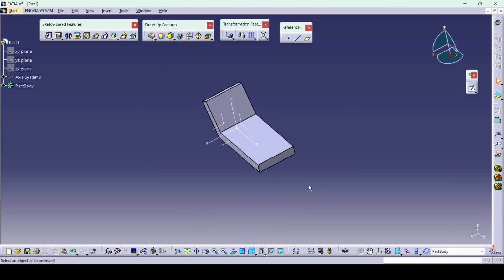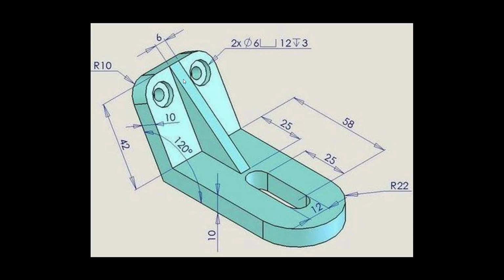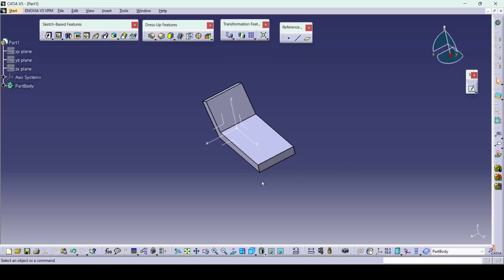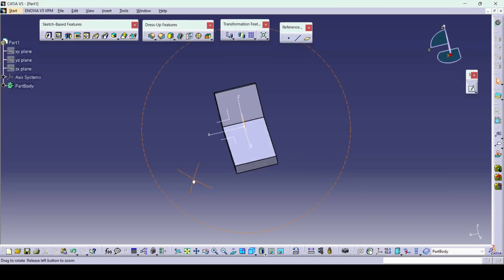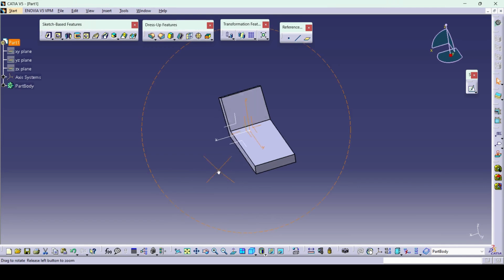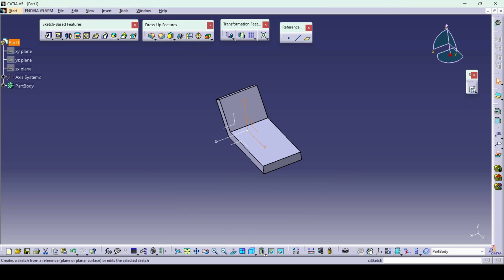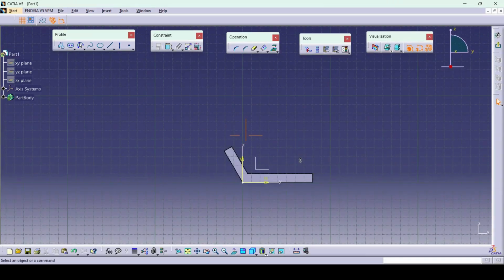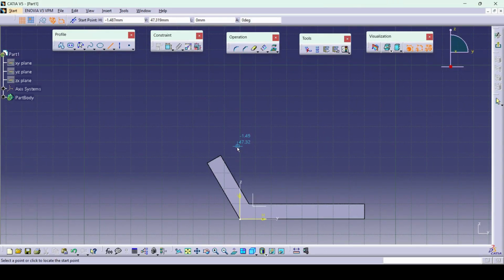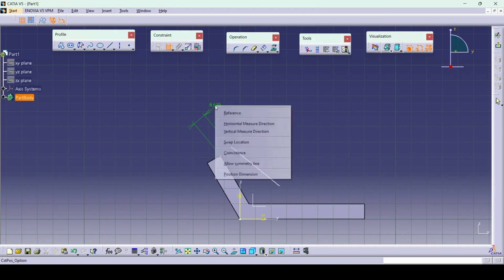Next to that, we have the addition of material with a width of 6 mm with this inclined line exactly at the center. So to create the profile exactly at the center, as you can see, we already have one plane here. So I will go on this plane for the sketch. Then on this plane we have one inclined line in this direction. Then to apply relation, I will go for constraint. We need a relation between this point and this point.